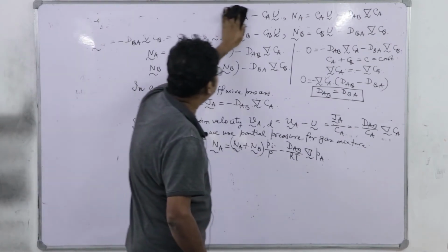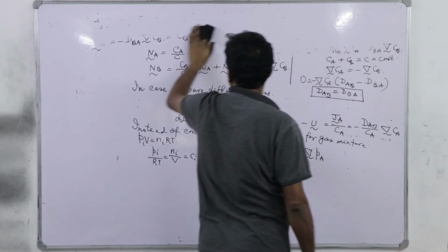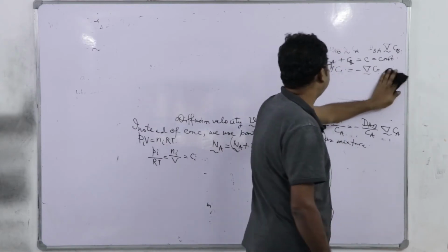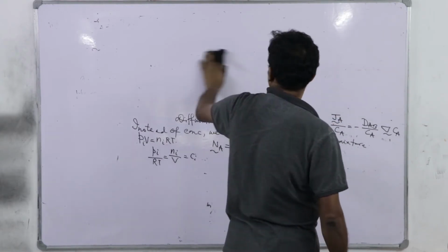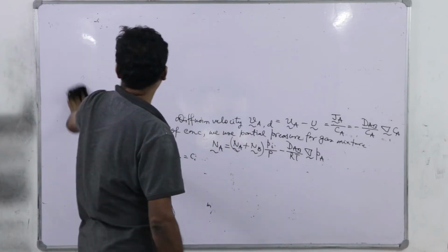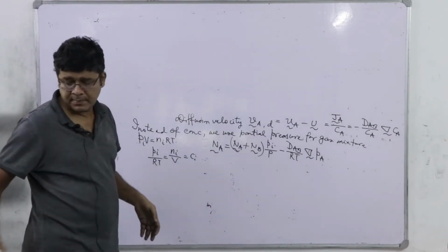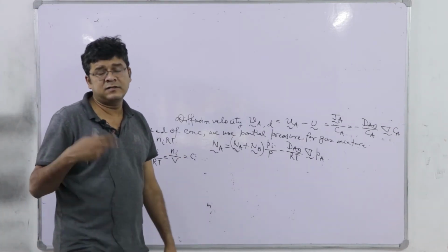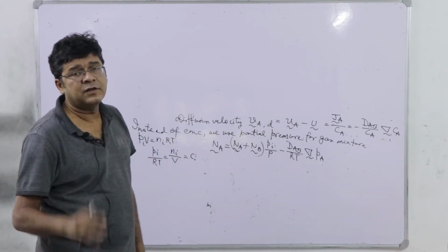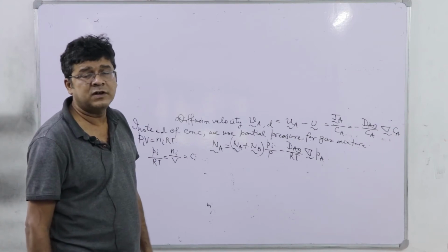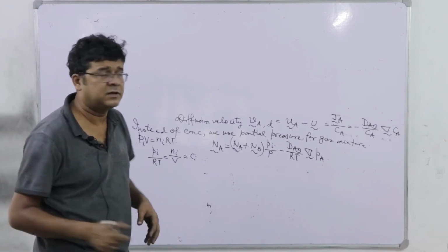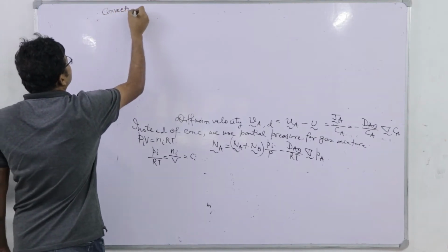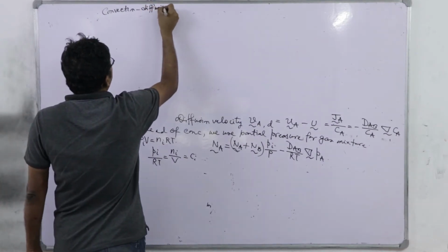Now, in conduction you see from this general conduction equation, we have from the Fourier's law, tried to derive the general conduction equation. So, here we will not do this same, but similar. We will use the convective contribution of transport simultaneously and also the contribution of reaction, right. So, we will get what is referred as convection diffusion reaction equation or sometimes advection diffusion reaction equation. So, we call it convection diffusion reaction equation.